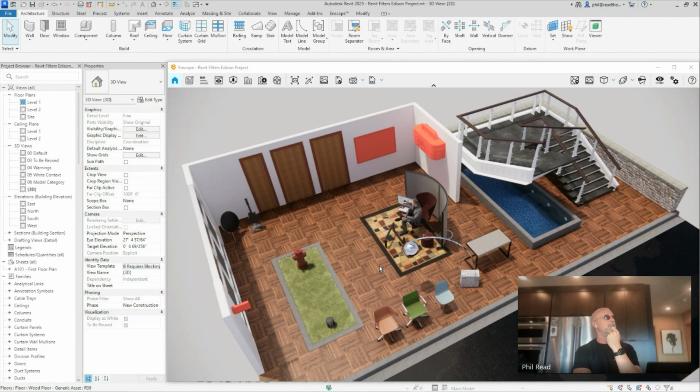Is there still that family parameter that says, when you create a parameter, it's shared or it passes through the family? Like if you create a table with 4 chairs and the table's the host, but the chairs don't share that, they don't schedule through. And I wonder if you tweak that value so that they schedule, then they're kind of also recognized. We'll have to check that out. Yeah. Anyway. So you're saying the host gets the override, but not the nested. Correct. All right. We'll have to look at that.